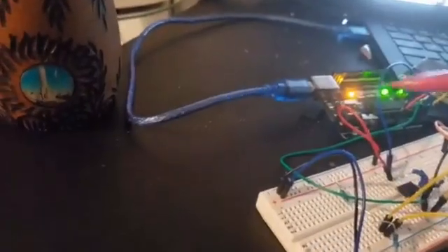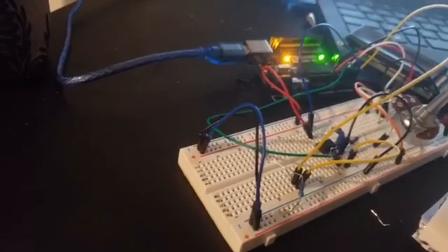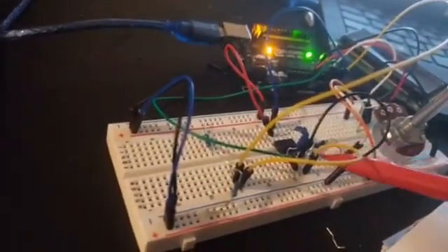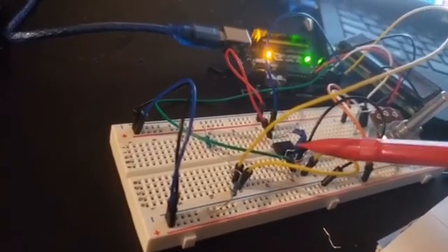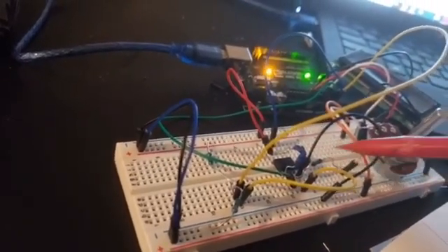Exercise number 3. Here you can see how I use a voltage divider in order to generate my artificial ground here and wire that up. And also my Vin is connected to a 1K resistor, which is at the same time in series with a 10K resistor, making a gain of 10, minus 10 for this, because it's an inverting amplifier.